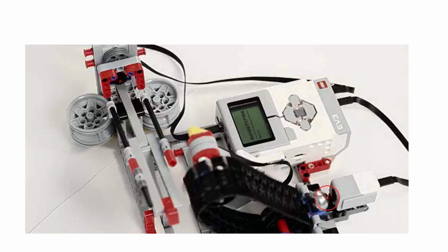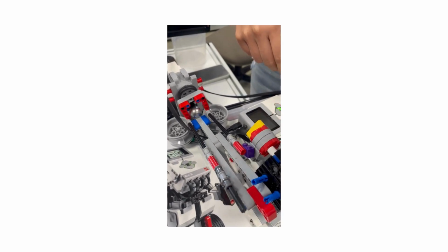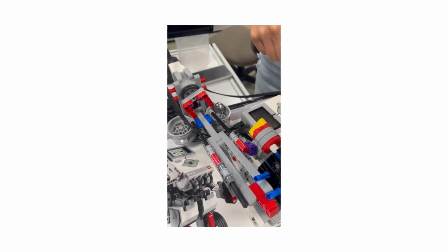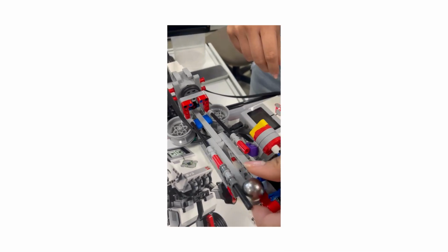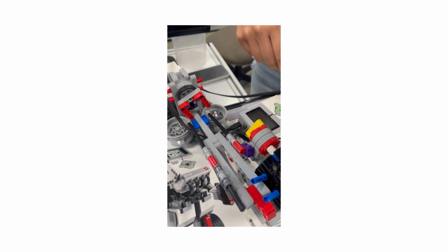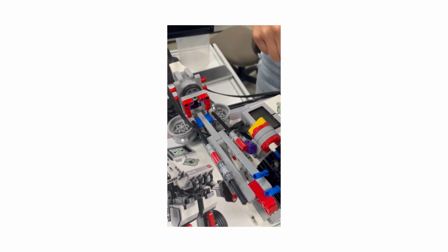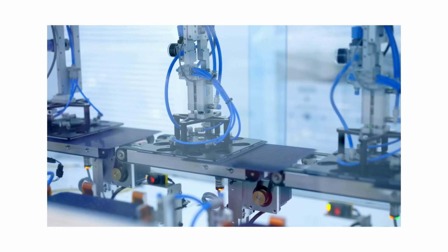During the project, we faced several challenges. Sensor sensitivity, because the color sensor sometimes misreads the ball due to changes in ambient light or shadows. And motor alignment: if the conveyor motor was not properly reset, the ball could start in the wrong position. Mechanical issues, like pieces sometimes becoming loose or misaligned, which reduced precision. And finally, programming errors: small mistakes like missing imports or symbols cause the program not to run at all.